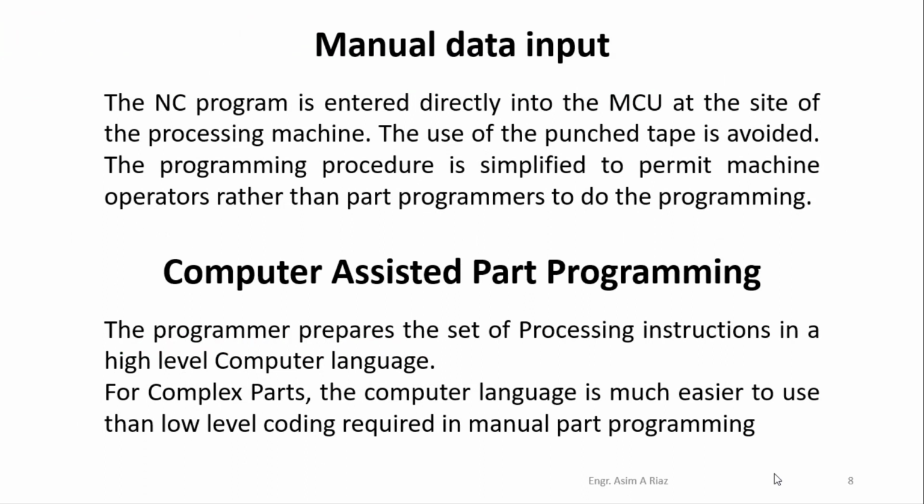Manual data input: the NC part program is entered directly into the MCU at the site of the processing equipment. The use of punch tape is avoided. The programming procedure is simplified to permit machine operators, rather than part programmers, to do the programming.